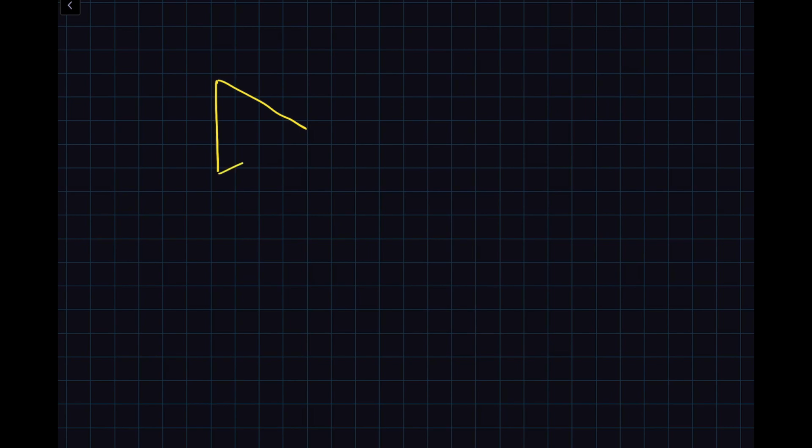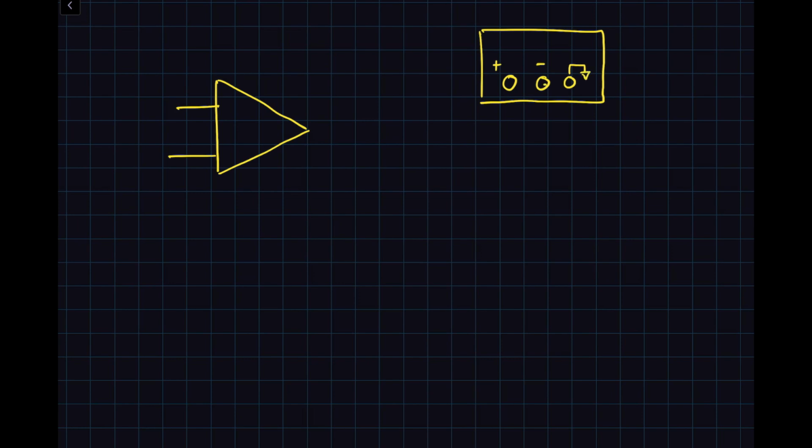However, let's take another example, which is most commonly used nowadays. Nowadays, you don't use dual supplies, you just use a single supply. Looking at the instrument, which is providing you, let's pick 1.8 volts as our supply. Then you will see plus and minus, and there will be a chassis ground. Typically we short these two, and here on the display you will see 1.8 volts. This is what you will apply to your amplifier.